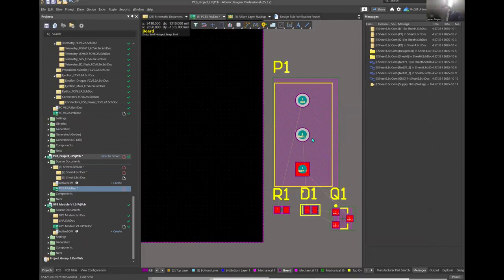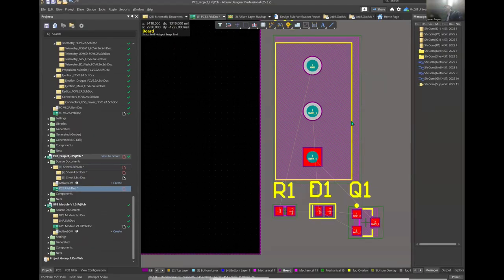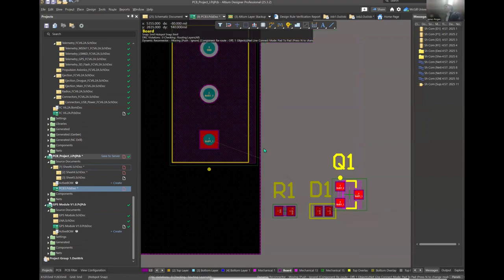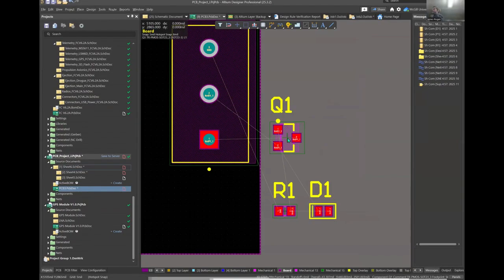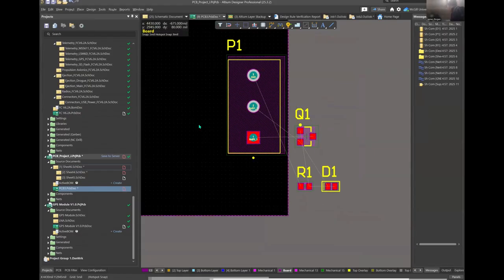You can see that there are little lines connecting the pads. These are defined by your schematic, where you define that a certain pin is on a certain net. It will show you the minimum distance between one pin on that net and another pin, which is super useful for component placement. So the first thing you want to do when you import them is organize the placement into subcircuits, where you try to optimize the length of the lines in the rat's nest.